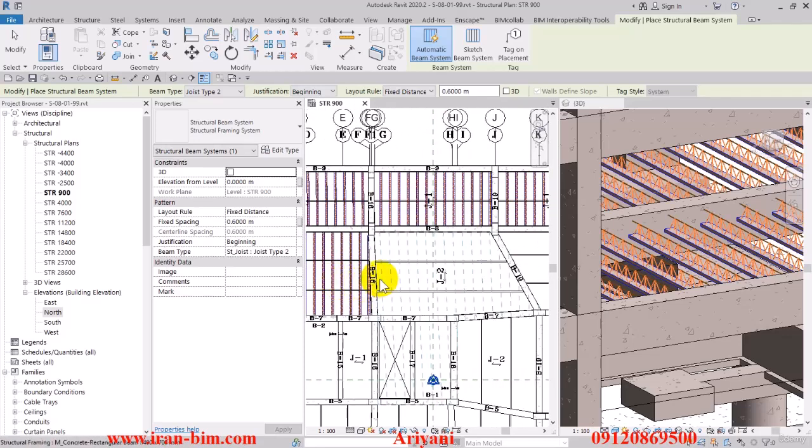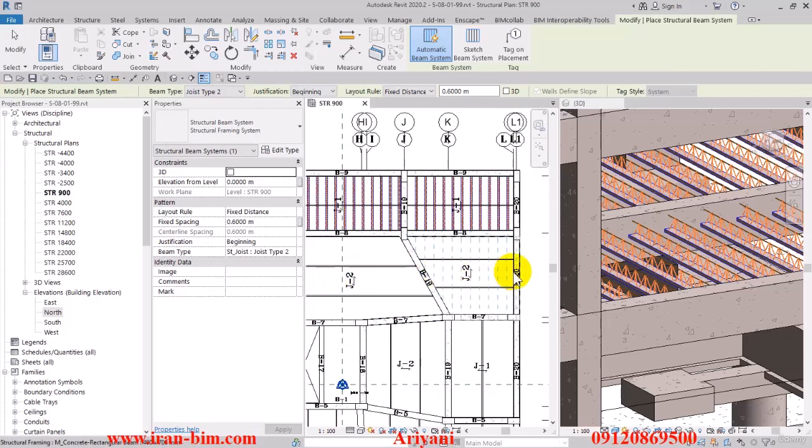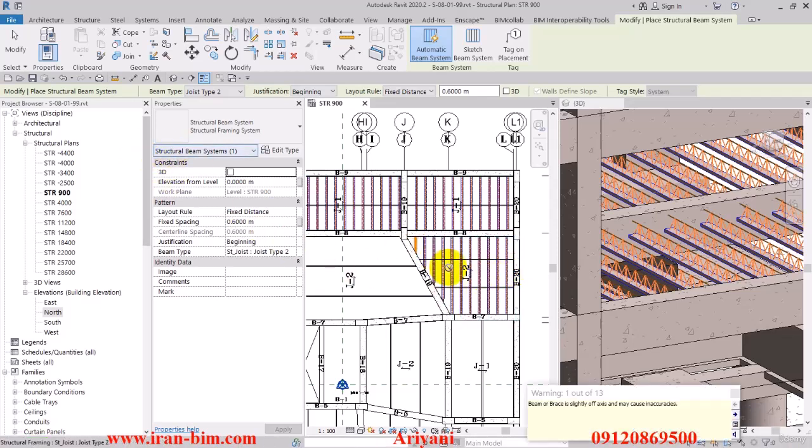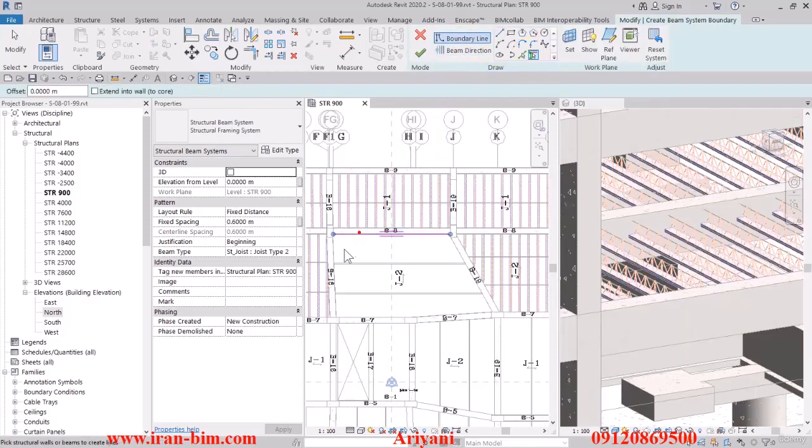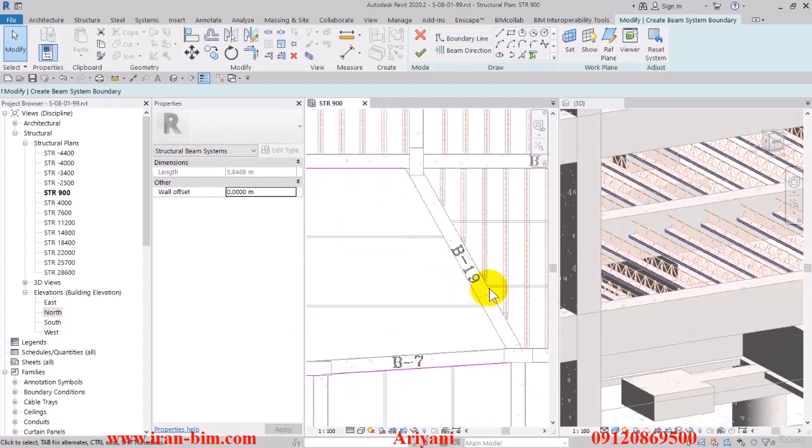All right, then we scroll over, and this area that we want to cover now also includes this part down here as well. So first I'll go to the right and draw this part out. Let's see, click on it, and then okay, and then we go to the middle part. In situations like these, we can use sketch. So here I'll go and select this beam and then this one, all of them around this area.